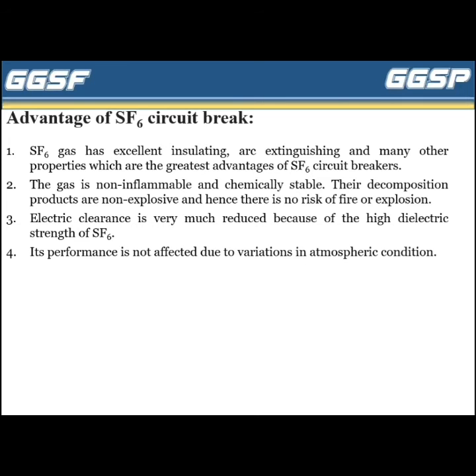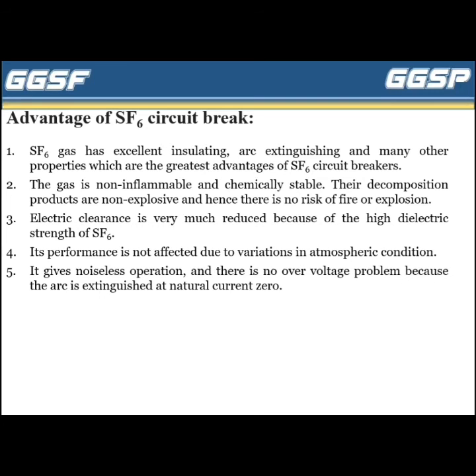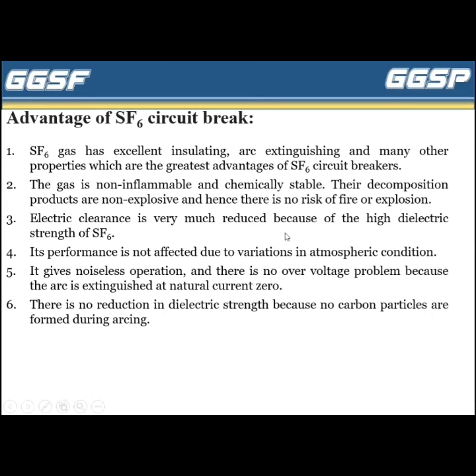Fourth is performance. Performance is not affected due to variations in atmospheric conditions. Fifth, it gives noiseless operation and there is no overvoltage problem because the arc is extinguished at natural current zero.